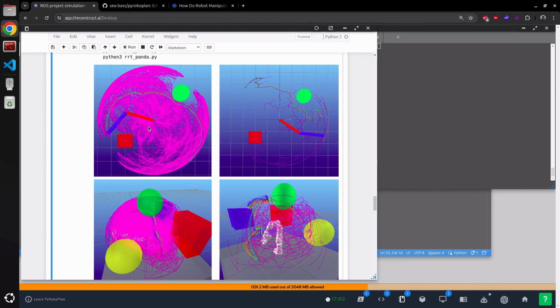It means that you can generate this big graph and use it for multiple motion plans. And then on the RRT side, these are less dense, but they have a finite lifetime. So when you plan an RRT, it only plans from start to finish, and then you throw away the planner.